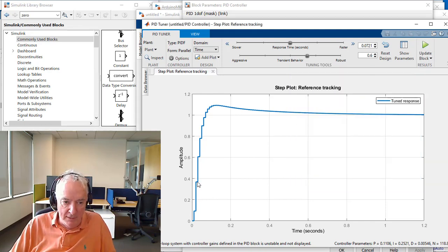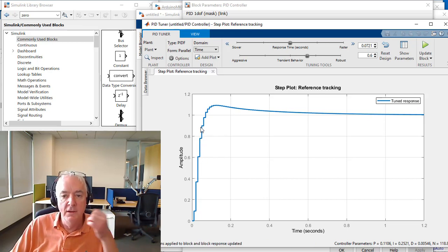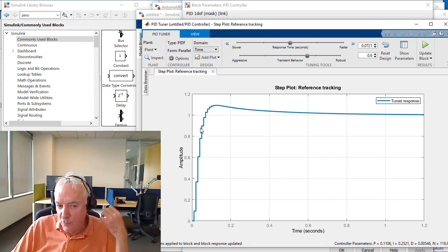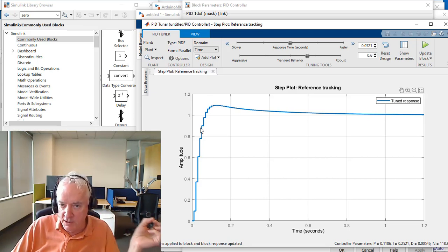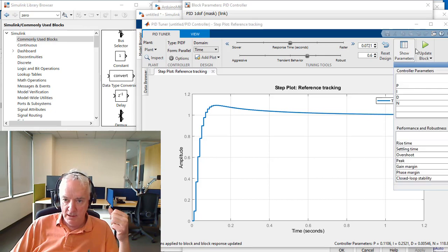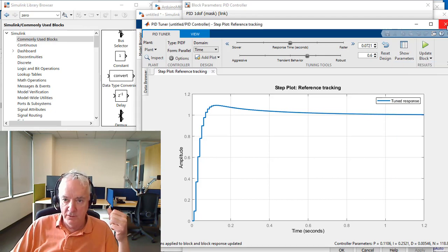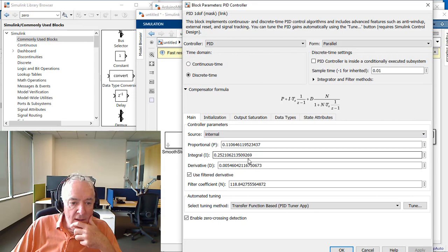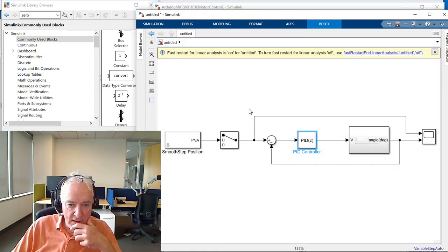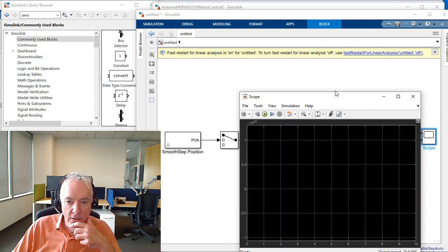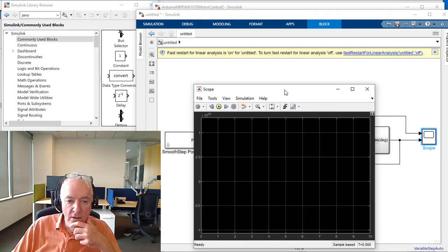We'll see that discrete time step taking place right there, in what I'd call the staircase form of the DC motor response, as discrete changes in voltage take place every 1/100th of a second. Is that updated? Yes, it is, so I think we can close this down. Those numbers are in there. Let's hit run again.